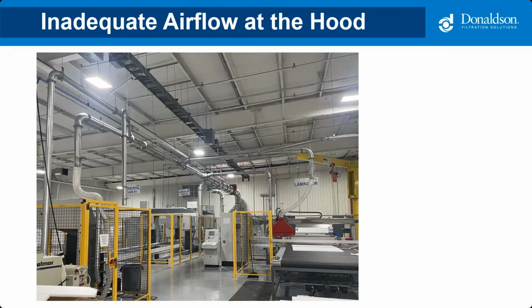So what's often recommended is 2 sets of slide gates. One slide gate typically up top where it goes into the main duct to balance the system, that gets set in place and left where it's at. And then you have a second slide gate near the tool that allows the operator to turn that particular duct off and on without unbalancing the system.